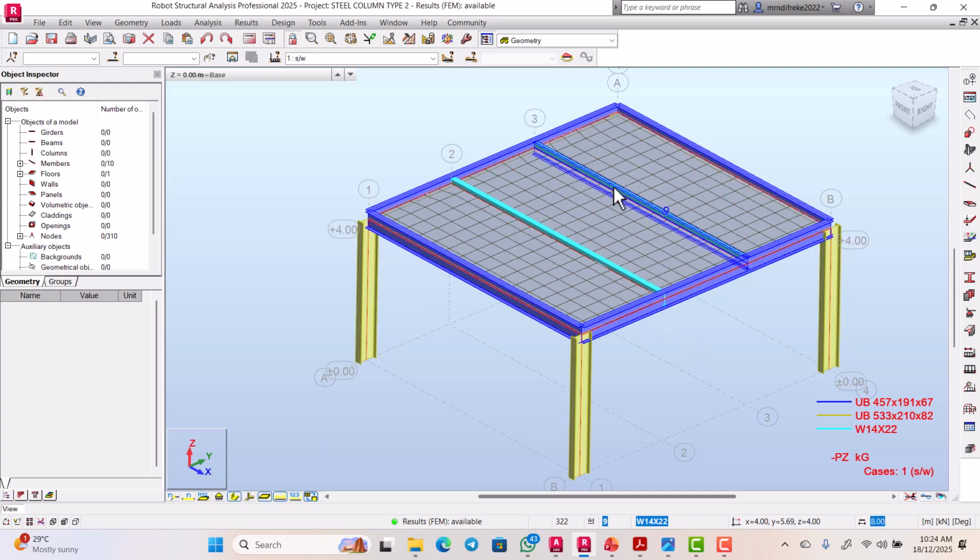So secondary beams are usually designed as restrained beams, while primary beams are designed as unrestrained beams. We might not say much about the unrestrained beam in this module until we want to design the unrestrained beam. So you must understand that a restrained beam is a beam whose top flange is fixed, restrained, or restricted from lateral movement. That is what a restrained beam is.